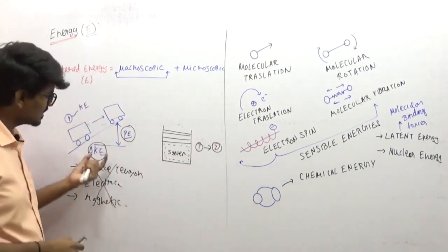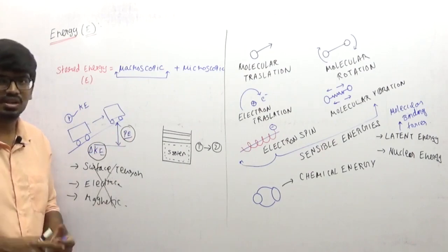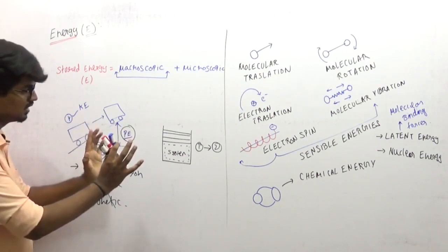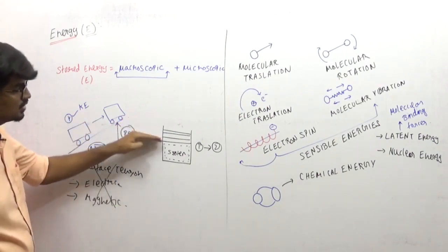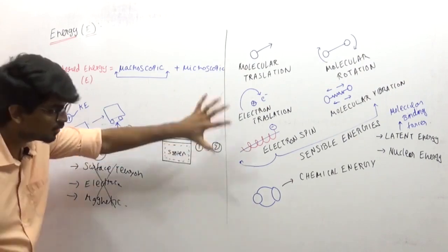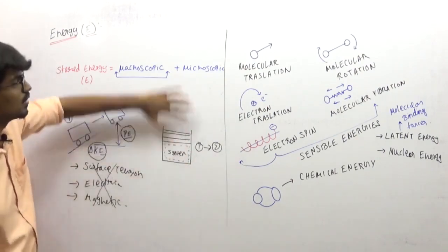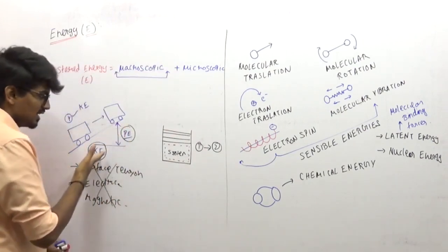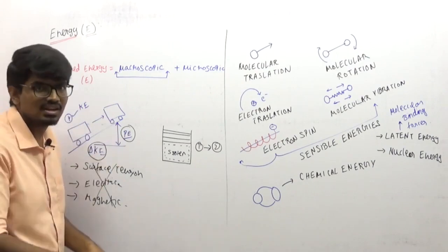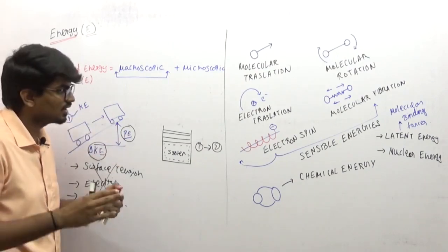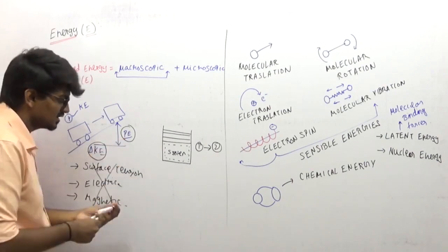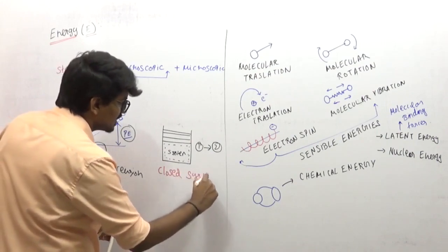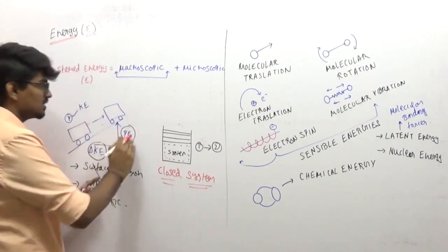How much is the change in kinetic energy or the change in potential energy which you could observe here as a whole, macroscopically? If you see it as a system, it is just getting lifted, but due to this lift, as a whole, the cylinder is not moving anywhere, it is not going up or coming down. So the change in potential energy or kinetic energy is very negligible. In fact, it is not at all there. There is not much change in kinetic and potential energy in a closed system. Of course, in an open system it will be there, and there we have to include kinetic energy and potential energy.